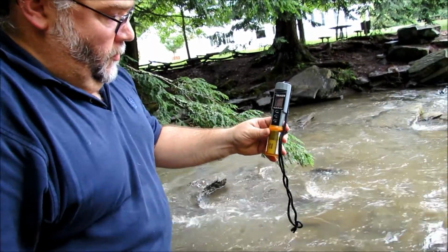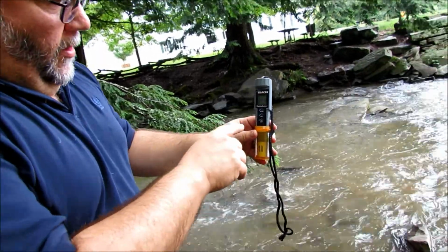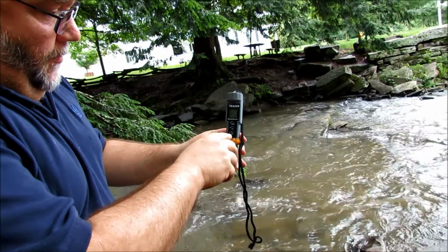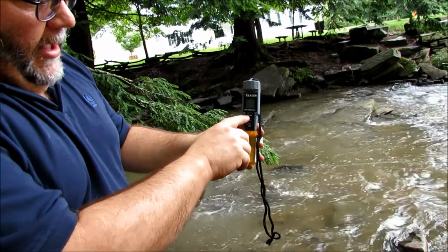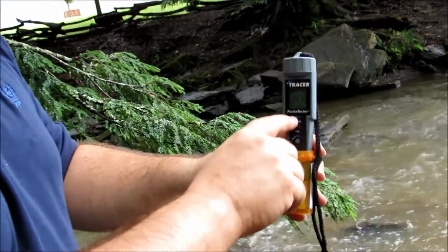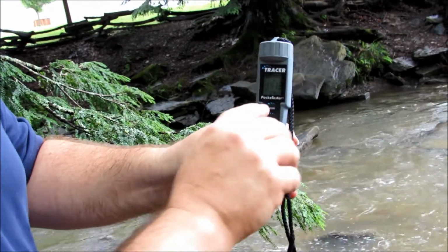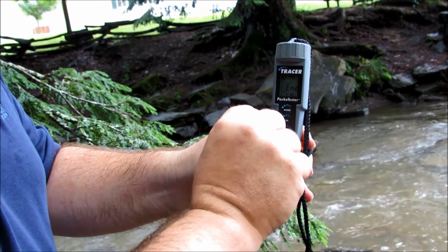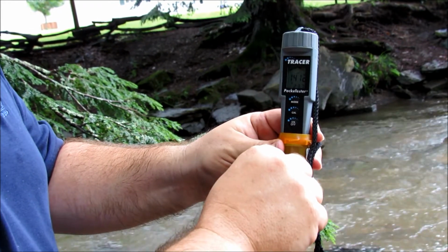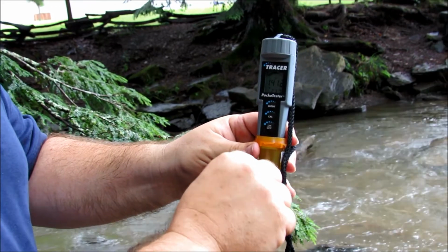So you're calibrating. We took it off, we rinsed it, we put it in a calibration solution. We had to change the mode to read conductivity. That's right at the bottom. It would come up conductivity, C-O-N-D, so we knew we're in conductivity. Once we put it in, we got it in conductivity.